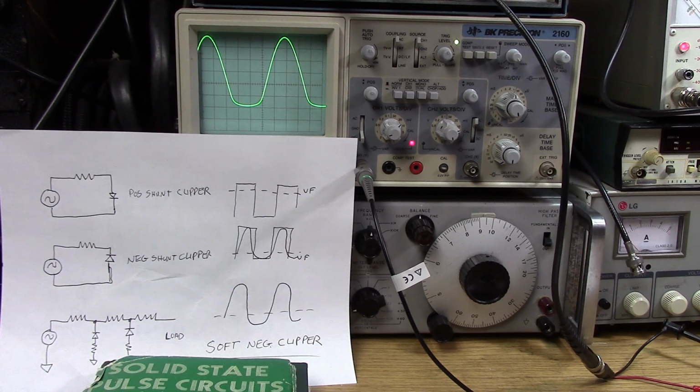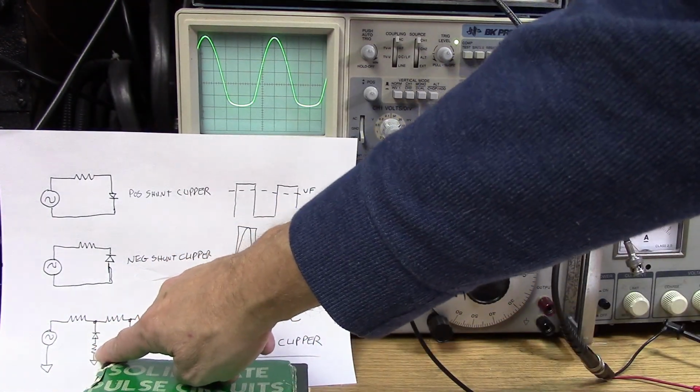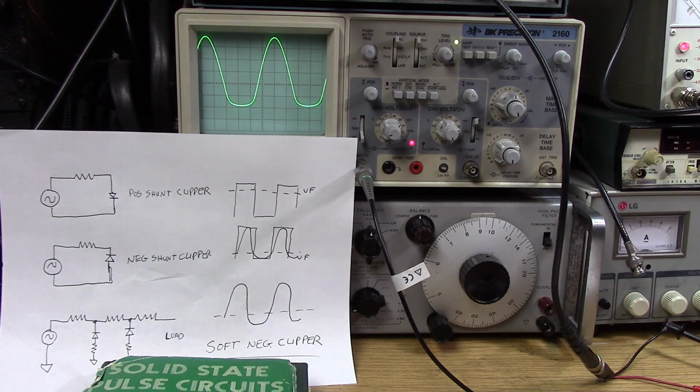Okay, so this is a single diode clipper. It really doesn't look too bad. The diode seems to be turning on okay. I'm putting in a reasonable signal, about 1 kilohertz. I guess it's 900 hertz. Okay, there's 1 kilohertz. And now I'm going to add the softening resistor. Okay, I'm going to add this resistor right here. Okay, I'm going to put that in.